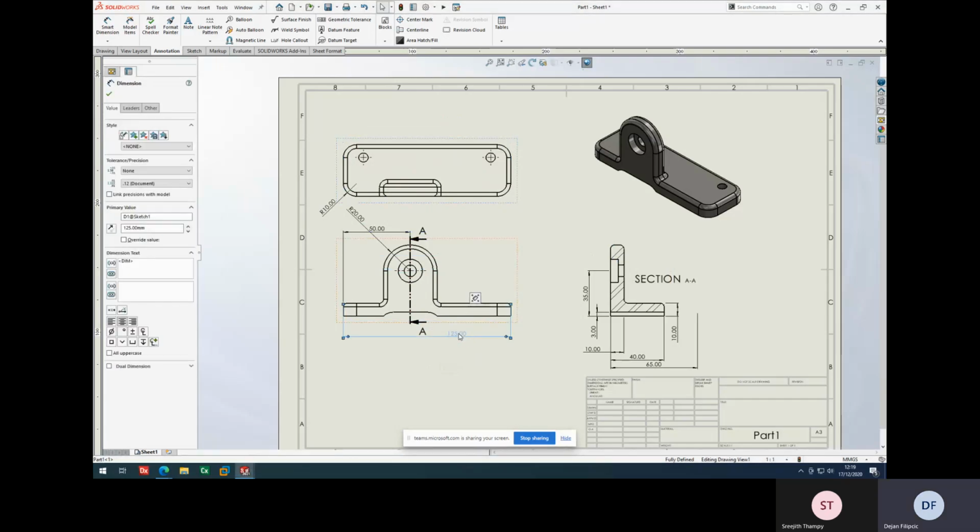There are different other things that come with the dimensions. You can see here, I can add a tolerance value. I can say how the tolerance should be, a basic tolerance, bilateral, limit, and all those, and the number of digits of the dimension. And if I have selected a tolerance, I can also set the number of digits for the tolerance.